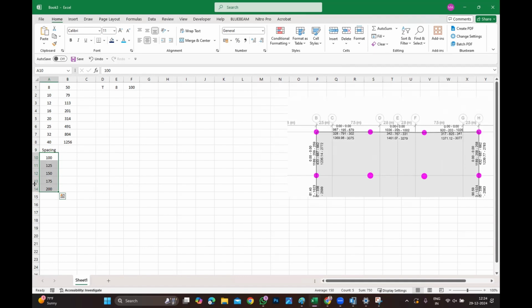The maximum rebar spacing is 300. Additional rebar you place in between, so the spacing only reduces; it is not going to be increased. But the main mesh is 200 only. Additional is okay, but the main mesh is 200 only. No one practically goes more than 200 millimeters. So I told you, what does it mean? T12.